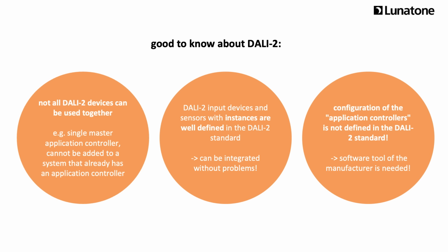And last, the configuration of the application controllers is not defined in the DALI-2 standard. Therefore, the software configuration tool of the manufacturer is always required for setup. This applies to both DALI control devices as well as interfaces to KNX, Ethernet, and so on.